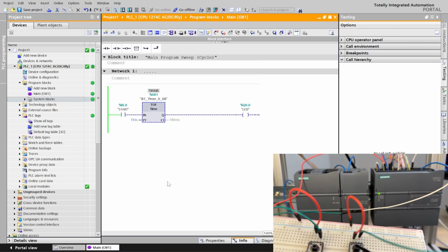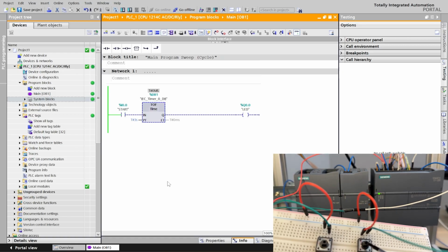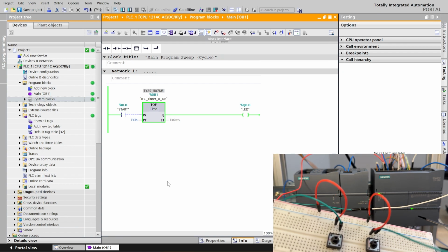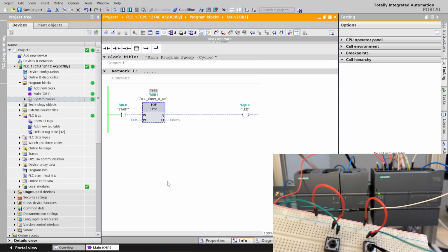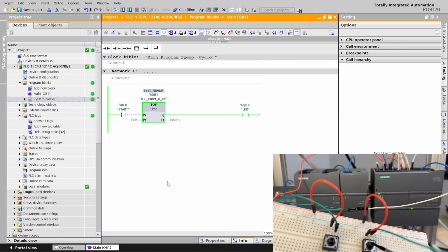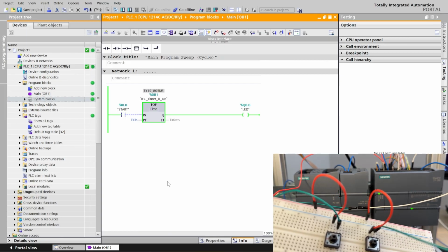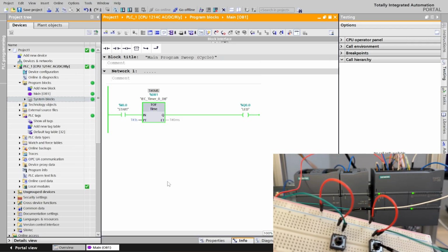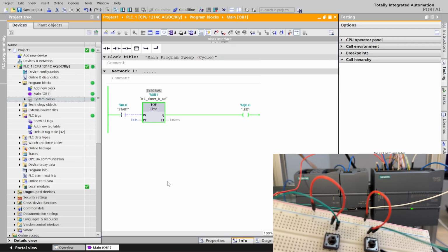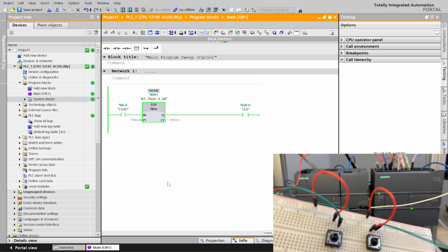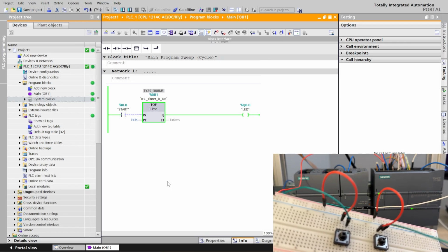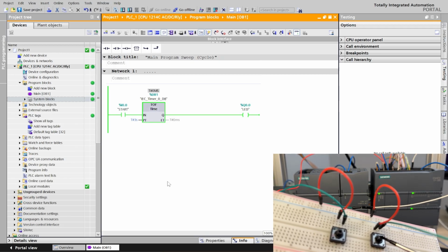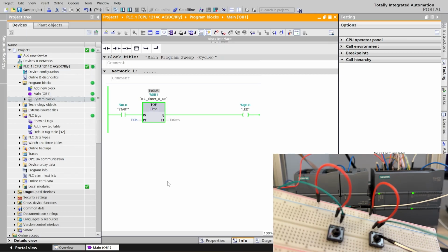load. So when I give the input, and if I give just a pulse, if I press it one time, it will stay on for 3 seconds and turns off. If I press one time and after 1 second press another time, it will reset and continue. Like if I press every 2 seconds one more time, it will stay on until the input is not pressed for 3 seconds, right? And if I press and hold it, it will stay on until when I let it